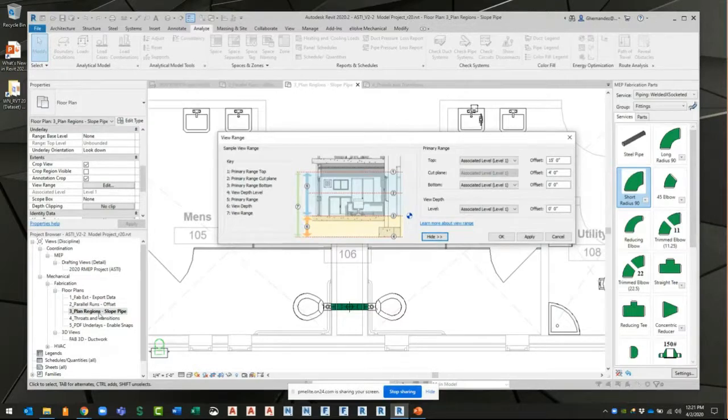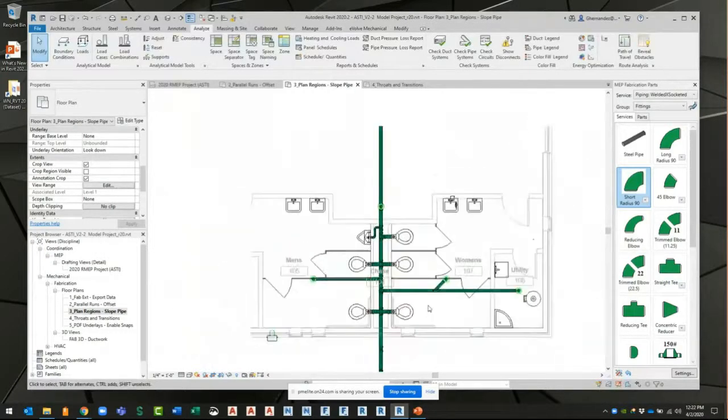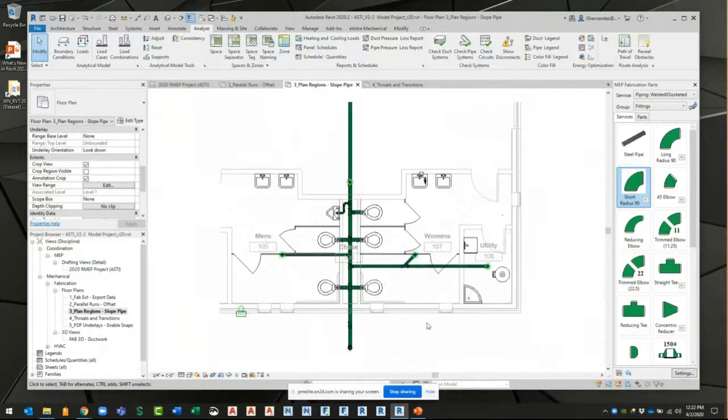specifically for a floor plan like this is set up to stop right at the top surface of the structure or the floor. So everything in yellow here you don't see, which would be typically my below ground sanitary lines that are at whatever slope values. But right now it's set to 0. So what you would do is set this to -4 feet, hit OK, and automatically and magically all your pipes underground show up, right?